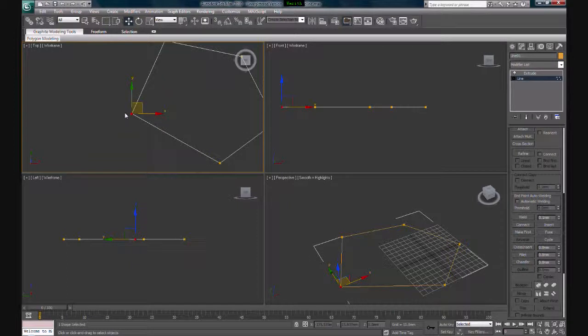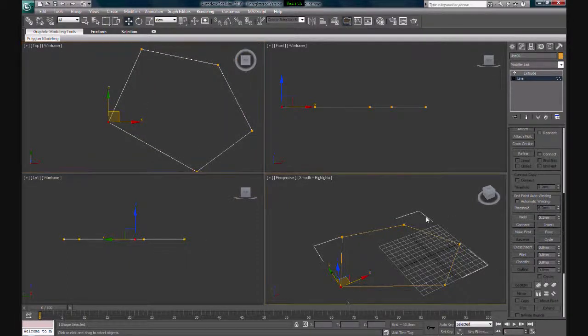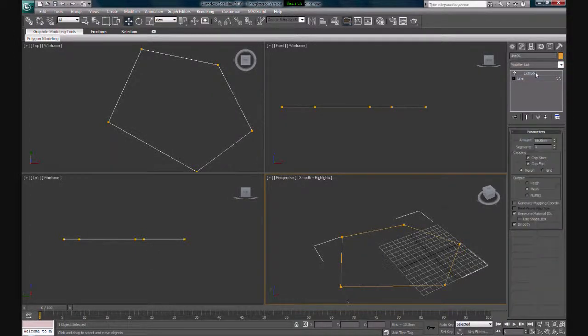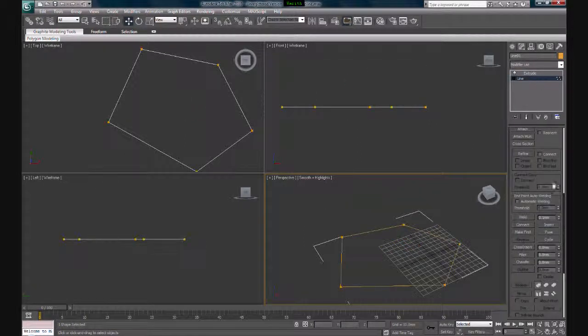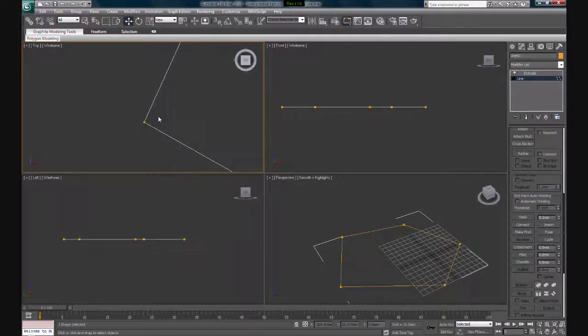So now it is important for you to weld it, because if you don't weld it, I'm going to show you. If you don't weld it, I'm going back to extrude. It will still be a paper thin extrusion, where there's going to be a void in the center. So I'm going back to line. The way to avoid that is, after you fuse it, you must weld it.